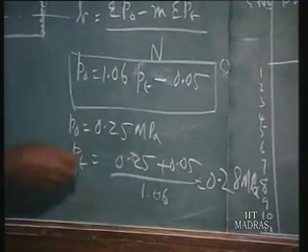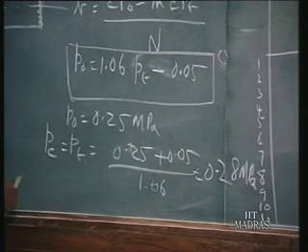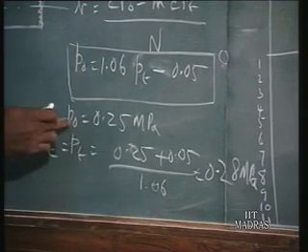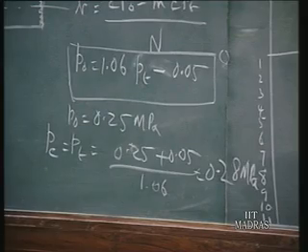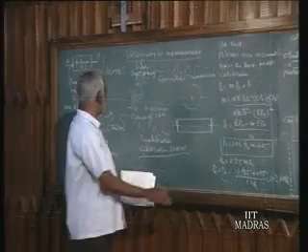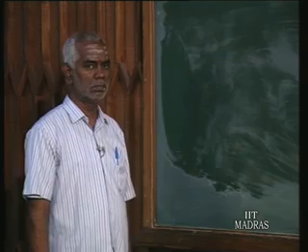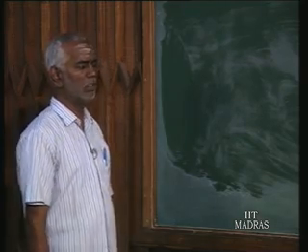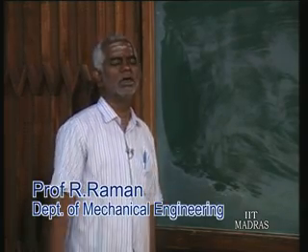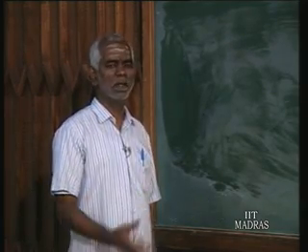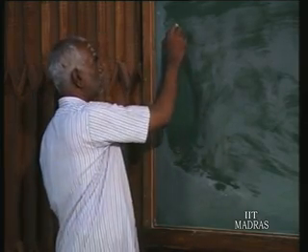So by using this equation we calculate pt, that is, we will call it again, name it pc, the corrected value. For p0 the corrected value will be 0.28 megapascal. Now the next step is we have to find out what is the error limit for this reading. Having found the corresponding corrected value, we have to find out the error zone within which the instrument gives a reading. For that we have to use the standard deviation,